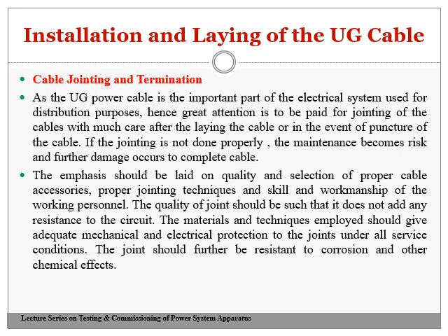First of all, you have to go for a termination. Once the cable is laid down, on either side a termination has to be provided. In this case, a termination means the connection of the two ends of the cable to the supply point, one towards the supply point, the other towards the utility point.